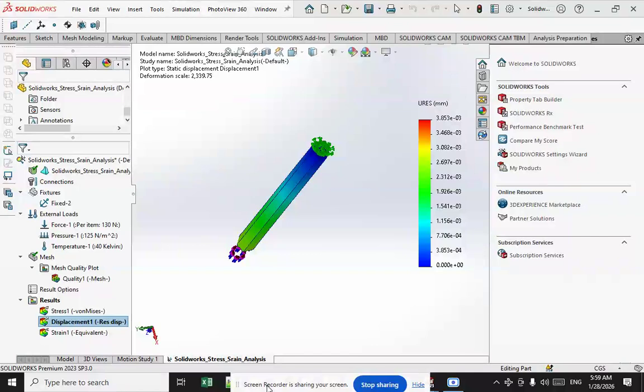If the stress distribution can be assumed to be uniform, or predictable, or unimportant in one direction, then one may use the assumption of plane stress and plane strain behavior, and the equations that describe the stress field are then a function of two coordinates only instead of three.